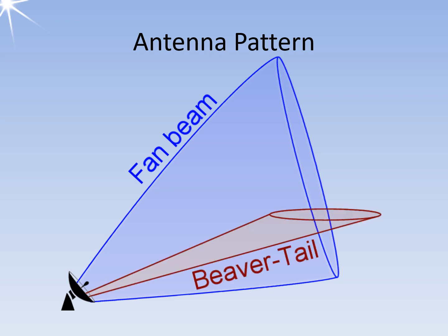This pattern was commonly used in early two-dimensional surveillance radars, but nowadays it is only found in low-cost radar sets. The fan beam could be rotated by 90 degrees and was used by older height finders with a nodding antenna to search for the third spatial coordinate. This up and down pivoting pattern was also known as the beaver tail pattern.